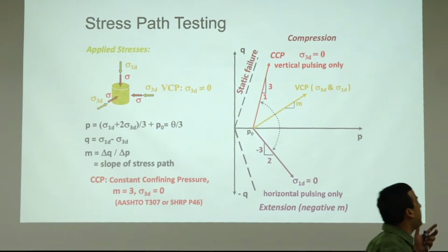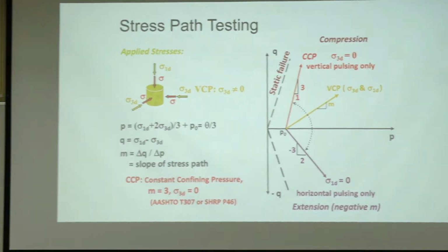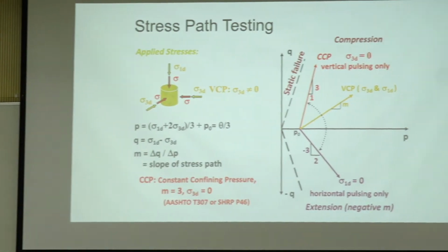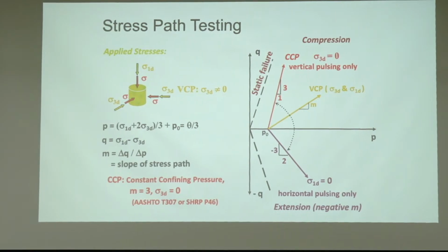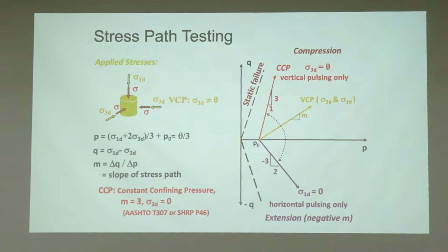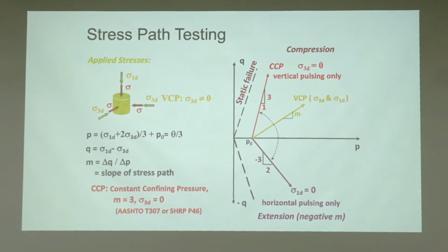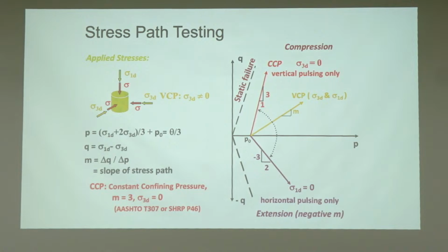Now when you try to do a complete model, and you actually say that, okay, this is where my wheels are, this is where my wheels are, and this is the stress path, let's just say you are trying to study a repeated load, like the NAPTF, the National Airport Pavement Test Facility. They have a huge system where they actually mount aircraft gears and they load.